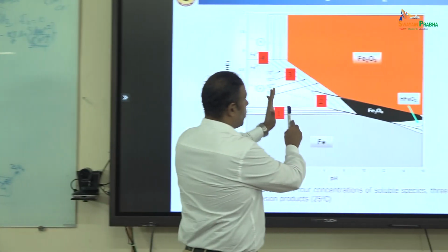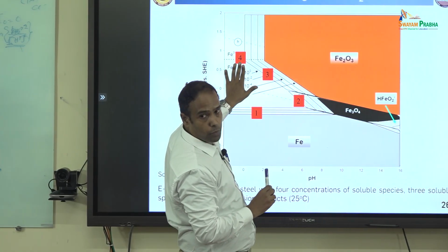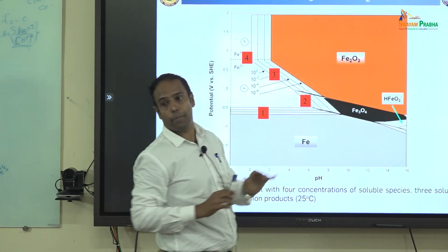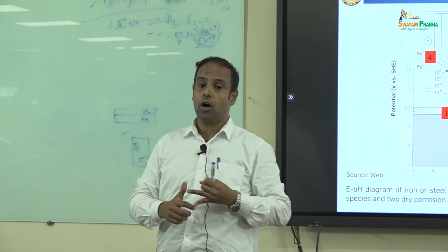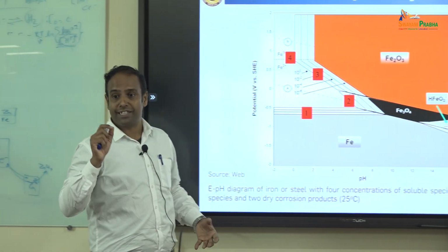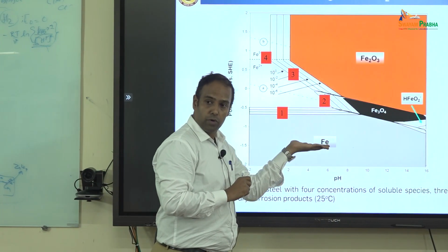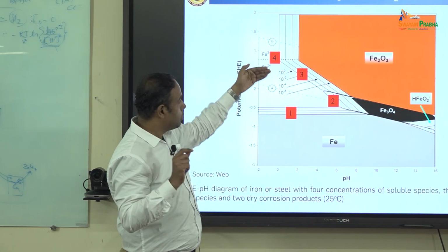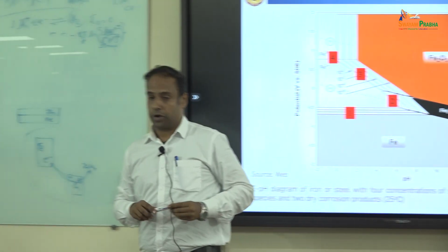Passivation. So, I can do anodic protection if I know the conditions. Instead of having iron Fe2+ here, I can shift the potential or the conditions of pH to bring it into a passive layer. That is called anodic protection by applied potential or by chemical passivation. So, the Pourbaix diagram gives me an idea about the thermodynamic stability of a particular system. Iron remains immune in the gray region, in Fe2+ in the acidic, in these potential ranges. So, I can use this concept to bring it as cathodic protection or move it towards anodic protection.